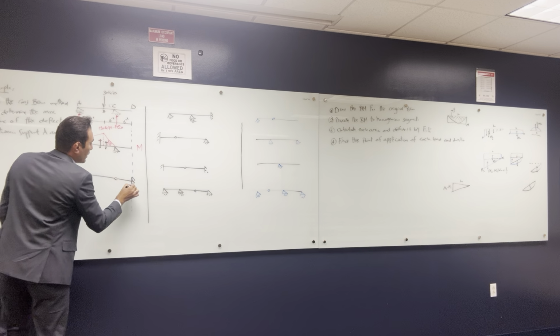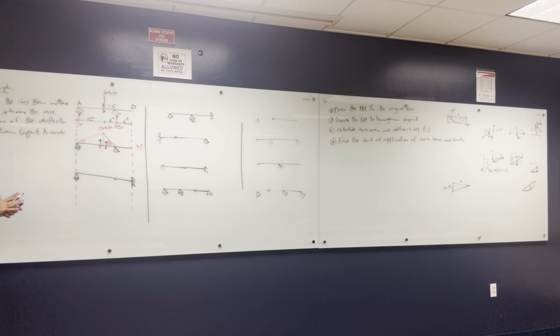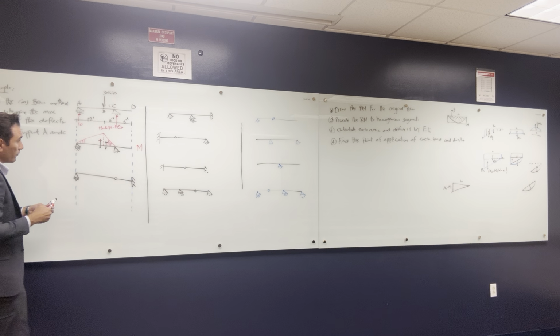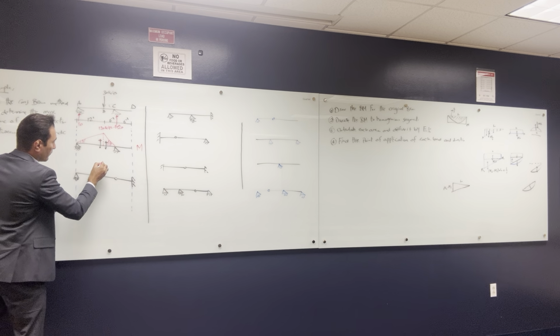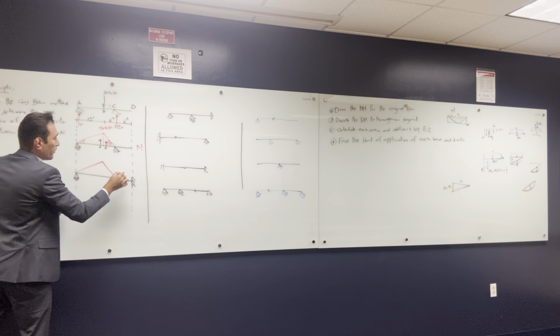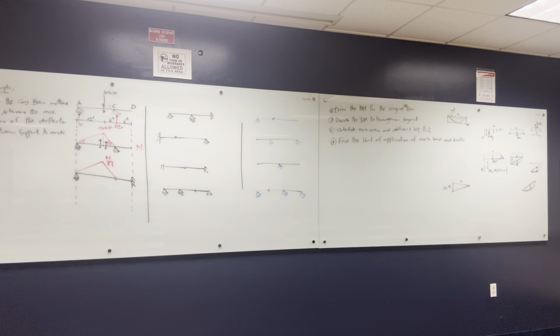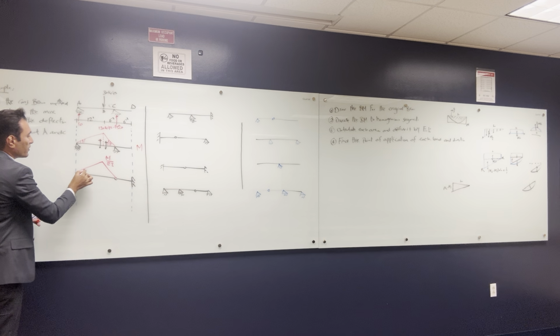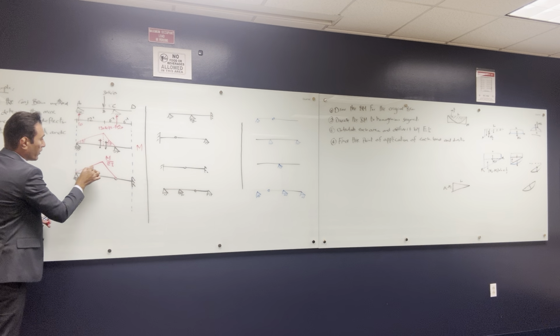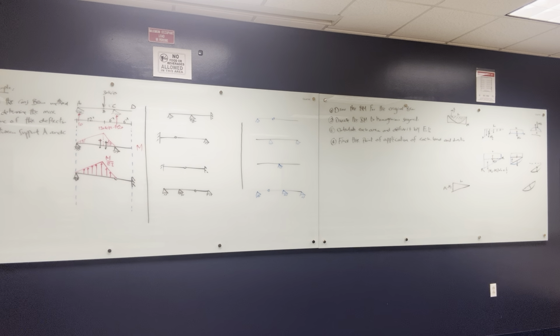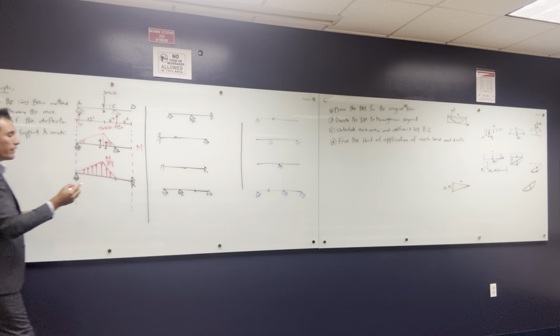Okay. Let's put the bending moment as a load on the new beam. So I'm gonna have this. Should I put M or M over EI? This is the conjugate beam. In the conjugate beam, we take the moment and divide it over EI, so it can be equivalent to d squared y over dx squared. And this is my new load, and it's positive. This is not a moment, this is a load. So I put arrows, that means that the load is going up, something like this. All right? Okay, so that is my load.